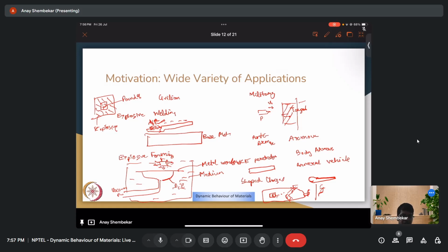From the results that he has been able to show, we have been able to tell what sort of microstructure we should have so that we disperse a wave quickly, which could come from, say, a projectile impact on a structure. So suppose a projectile hits the structure, then what sort of microstructure should be inside that structure to quickly dissipate that wave so that none of the energy transfer goes into the critical parts of the structure.